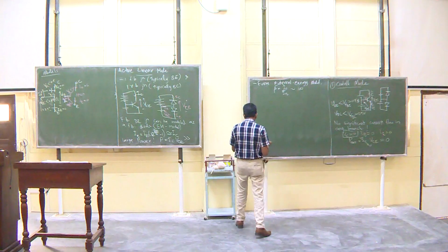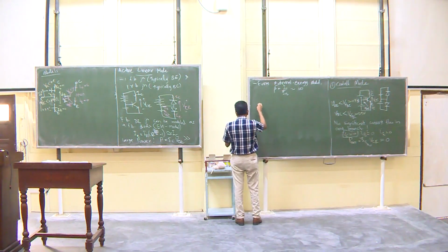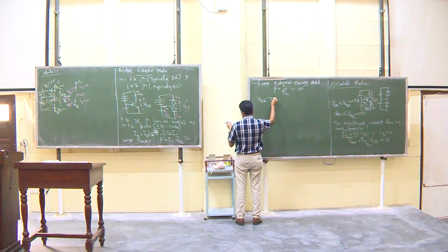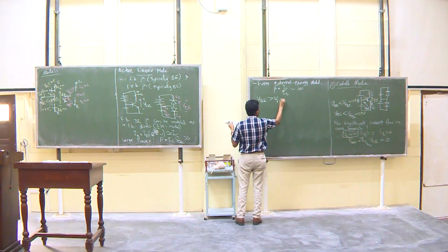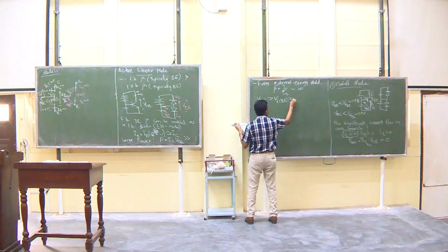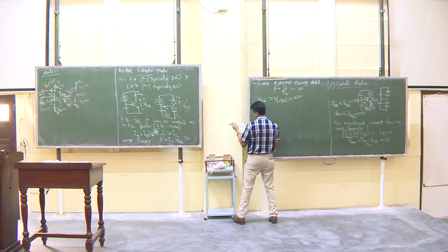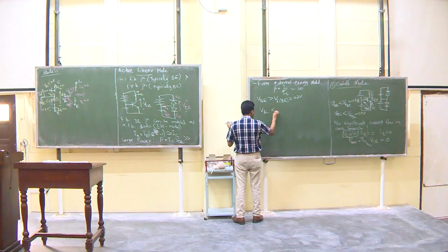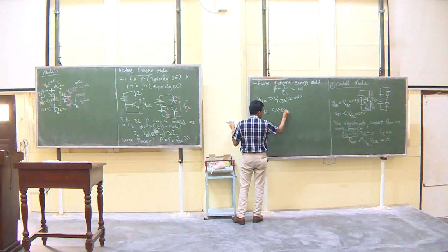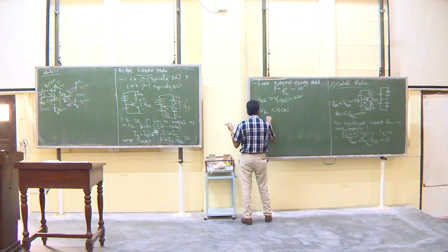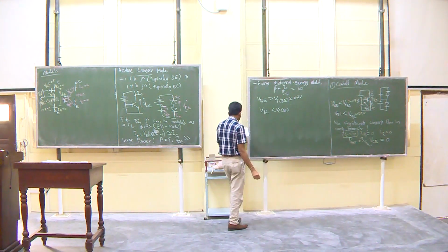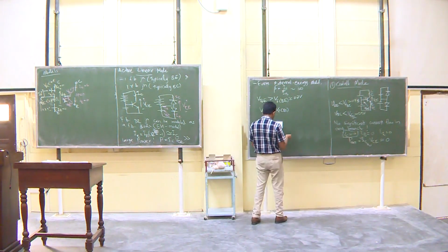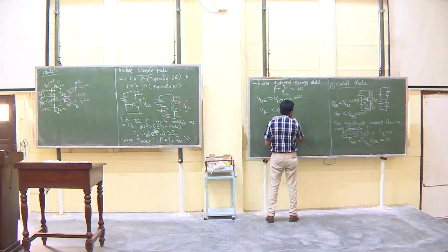Okay. So, under such situations VBE is greater than the forward bias voltage of the base emitter junction, so it is roughly about 0.7 volts. VBC is less than the forward bias voltage of the base collector junction, which is 0.5, so less than 0.5. So, we draw the model of this in the following manner.